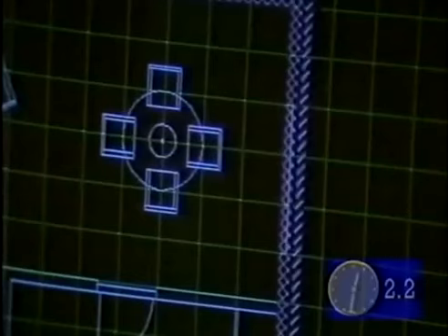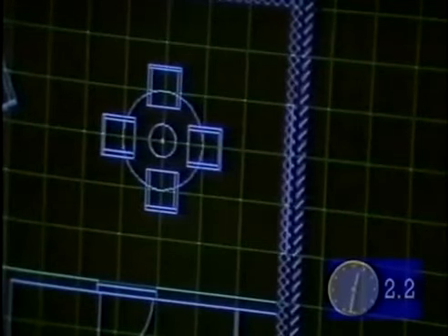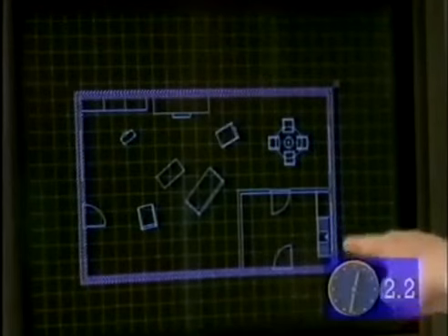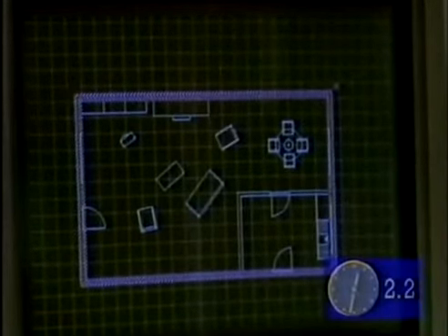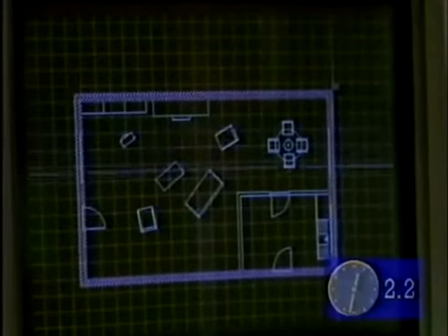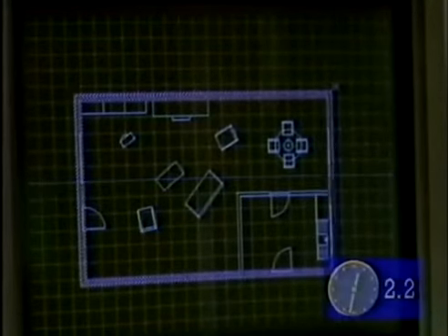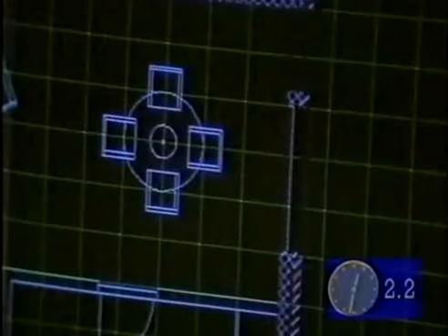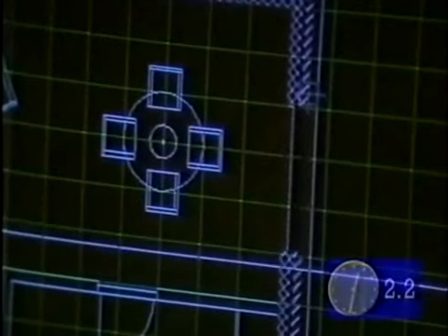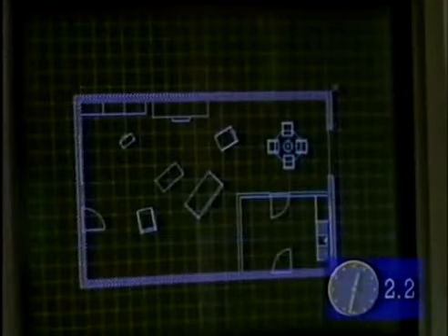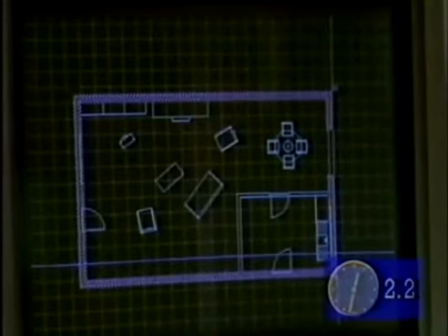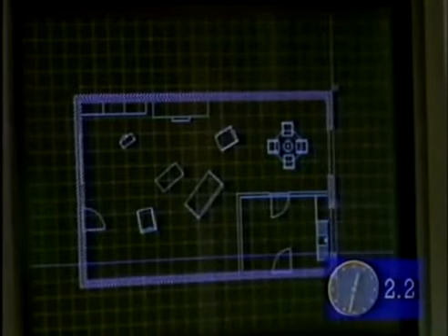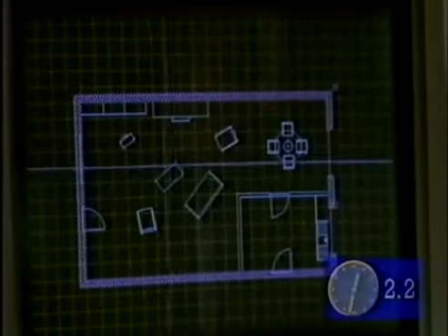And there are several ways of putting in the window. We could issue a command a certain distance from there. So if I said 600, it would move along there and put the symbol in for me. I'm going to use the actual J option, which allows me just literally to sketch in where I want it to go. It erases where it was and then redraws it in. So again, I can do that one. And it closes the ends of the walls and puts in the top view of the sill, which is in effect sort of retrimming.